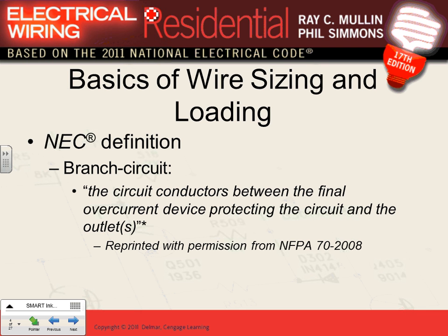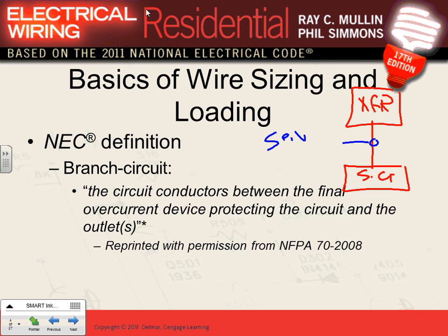Before we start, guys, with anything else, I want to remind you of the three circuits. If you graduate from Dunwoody without knowing these three circuits, don't go work. Three circuits. Circuit number one is the service entrance circuit. Anybody knows what a service entrance circuit is? If you start with the transformer, here's my XFR, my transformer. The circuit all the way to the switchgear, the power. This circuit is called service entrance. Service entrance circuit, right? These are the cables that bring the power to your service switchgear.